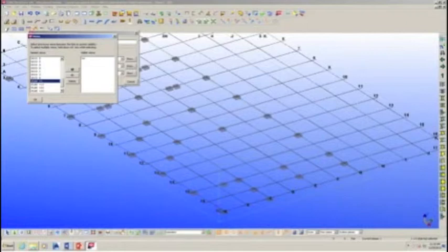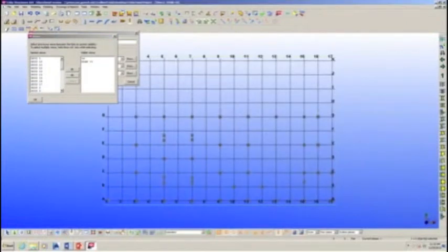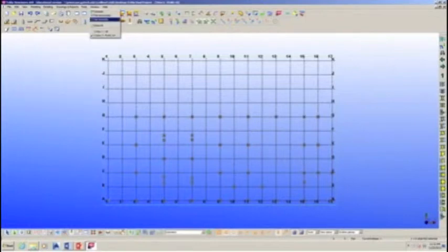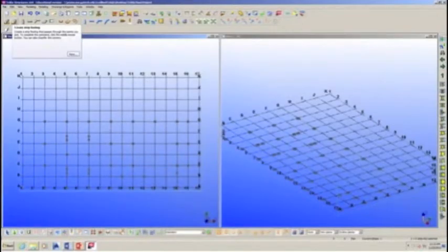Select the top arrow pointing to the right to move your desired view into the Visible Views column. You can already see the new view. Select OK. You can see and work on both of the views at the same time. To do this, select Window and then select Tile vertically. Now you can see and work on both views at once.